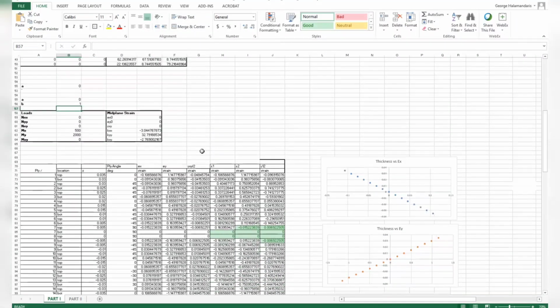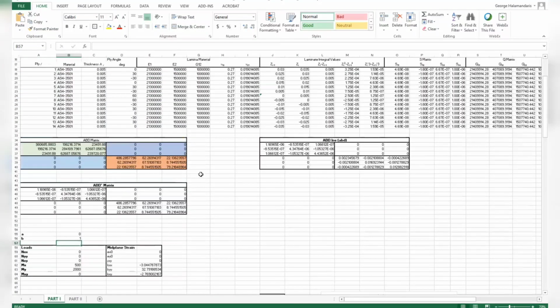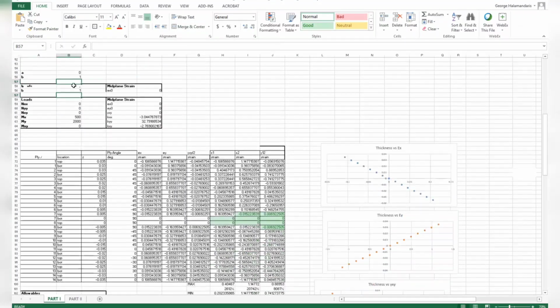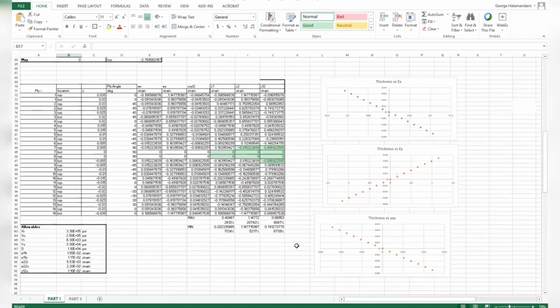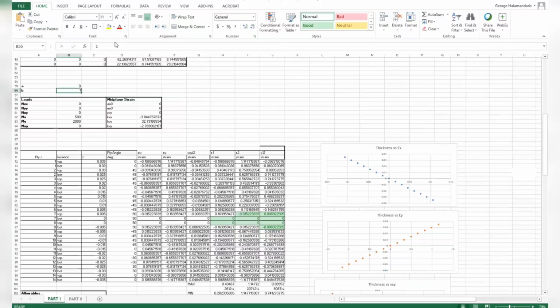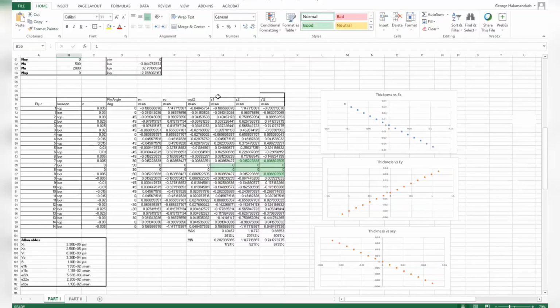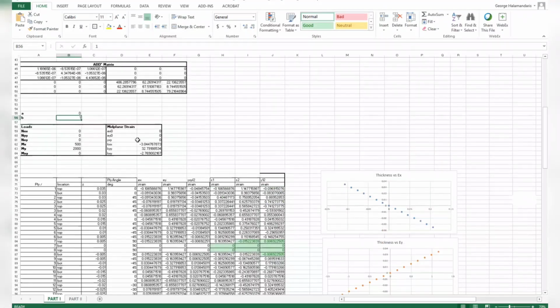So B, you notice this laminate is a very thin laminate, probably not super robust against moment. So B here, B was one, showing massive exceedances, like 20,000%. So again, you can follow the same workflow and vary B in order to show passing for each stress-based criteria, strain-based criteria, and Hoffman.